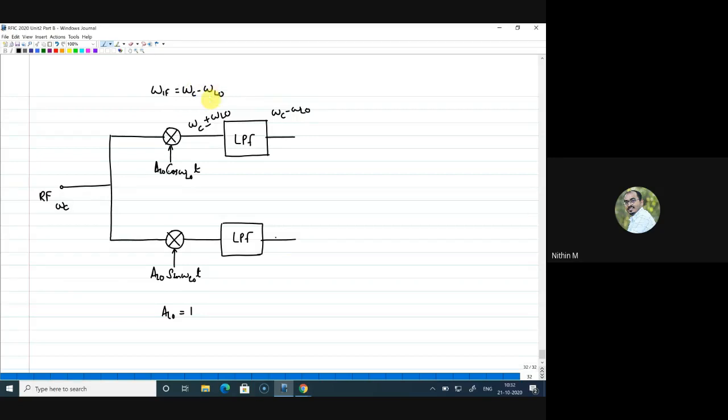Now, after low pass filtering, what we have done is we have applied a 90-degree phase shift to the Q path or the quadrature path. So here we have to apply a 90-degree phase shift. That also we have done. Now the result from here and here, if I add these two together, this will end up in an IF output where the signal components will be added up and images will be rejected.